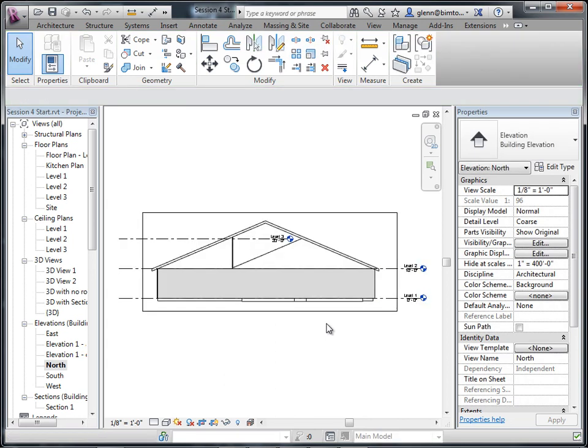Okay, so it all starts with this notion of really, what is the crop region? Now, how much zoom do you want? Or it's the scale and the crop region. So those two things really figure out how big that thing is actually going to be and what the bounds are going to be that show up on the sheet. So that's your first task, always, for each of the different views you're going to put on a sheet: crop it and scale it so that it's an appropriate size and an appropriate bounding box so that it's going to be what you want to see on the sheet.